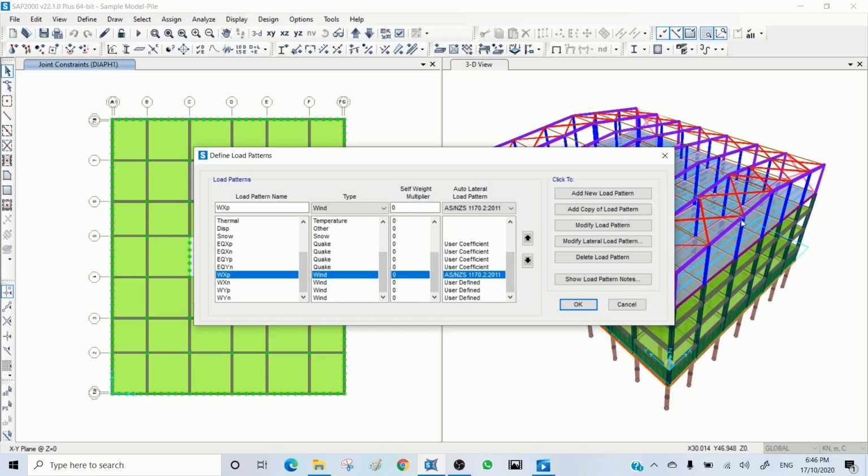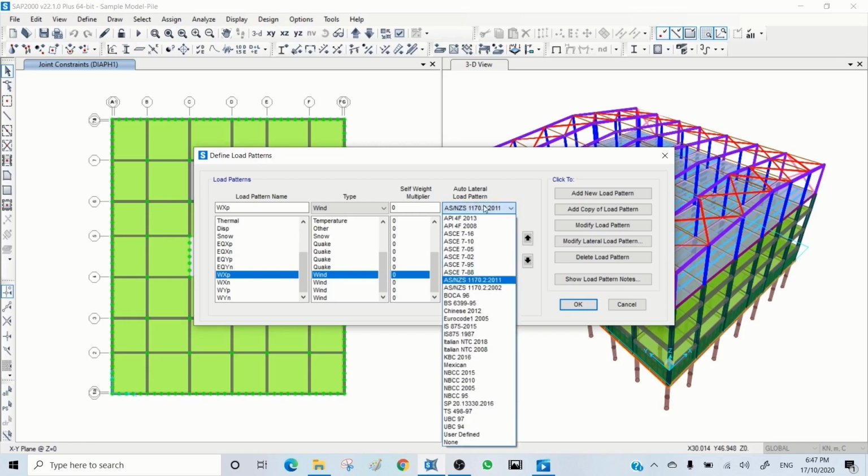We have roof load, we have internal pressure, and we have different factors, because when the combination of all loads are in the game, you don't have to apply 100% of all of them. It could be up to 80% of each of them. So I do prefer to do it myself.